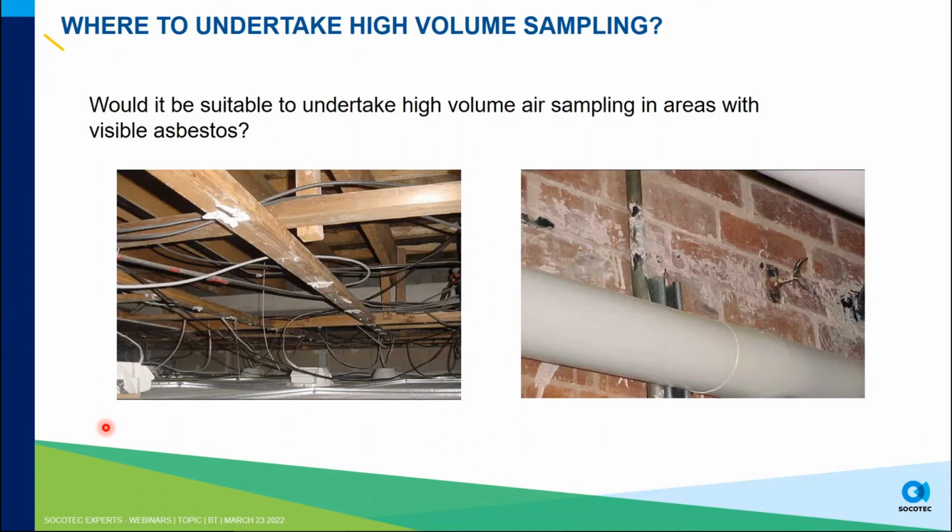I would probably start by saying probably not. We probably shouldn't be doing that. What we should be doing is using Regulation 4 and managing that risk by either isolating these areas, restricting access, preventing people from being exposed, and putting an abatement program in place to remedy that situation at some point in the future. Taking some air tests to confirm that the area is below 0.01 or much lower is not going to prevent anyone from being exposed. In these sorts of scenarios, Regulation 4, duty to manage, you must manage that risk accordingly.